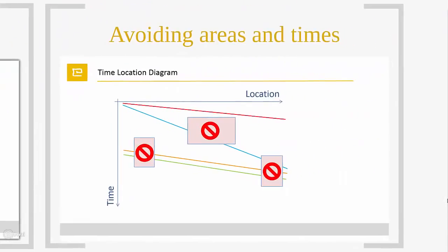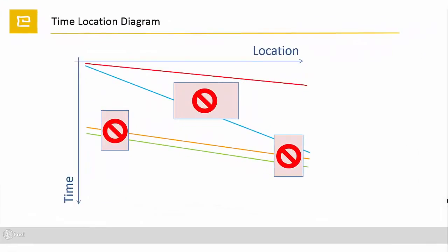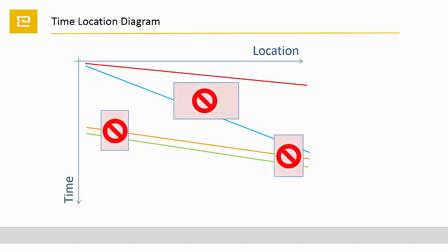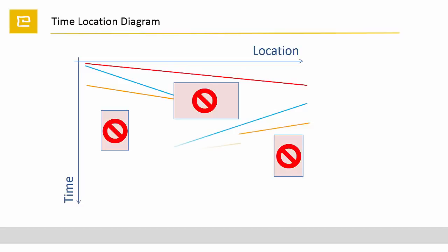The next sample is showing how to avoid areas due to legal restrictions, access rights, environmental protection or weather conditions. As you can see, just 4 linear activities are planned for this area. But what if you have no access on specific locations at specific times? How do you have to change the schedule? The clue is first locating the blockings, then fitting the task in the remaining place. Sometimes you have to cut the process and relocate the equipment, but in some there is an optimized schedule still very near to the original duration.